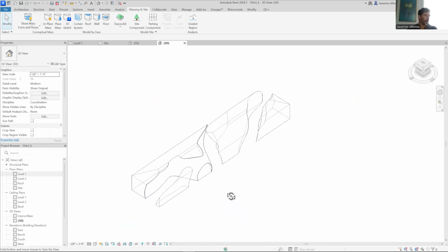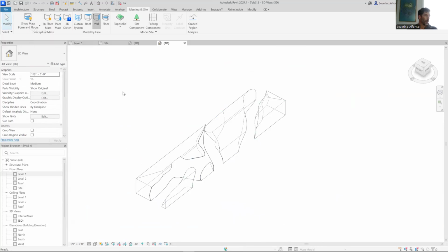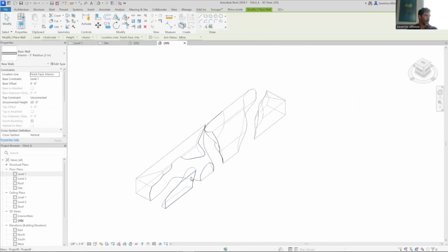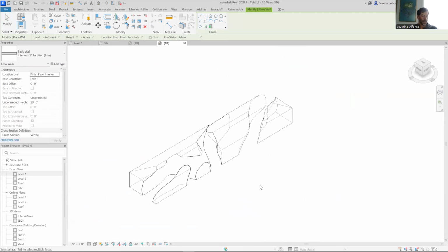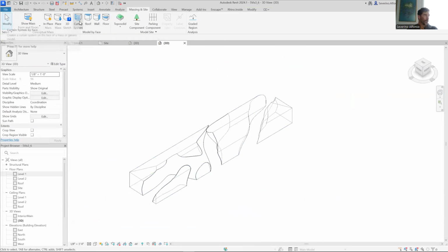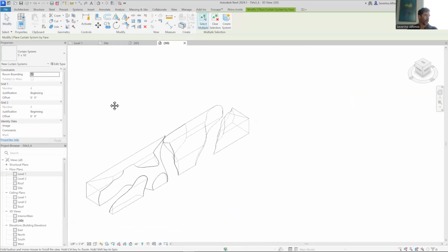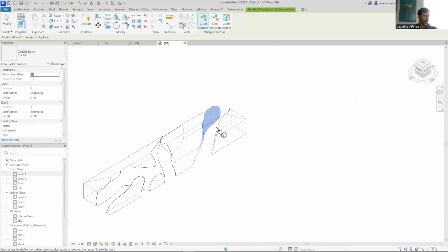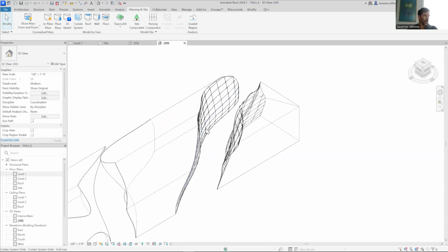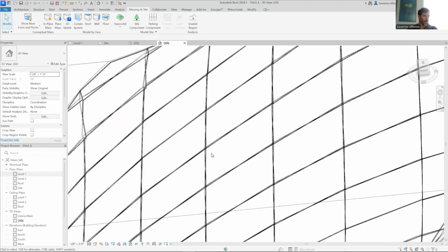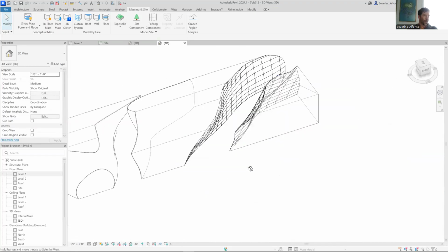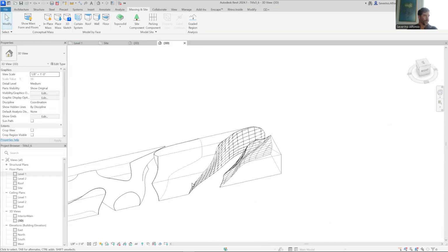This is what we're going to be doing a little bit. Just going to select some walls, maybe select this face, maybe select this other face here. And then I'm going to escape that to select curtain systems instead of walls. By the way, I could select different types of walls, curtain systems. I can select this other face and this other face and say create system. And a curtain system basically is a set of glass panels that are flat and they're cut at different patterns. We will be able to change that.